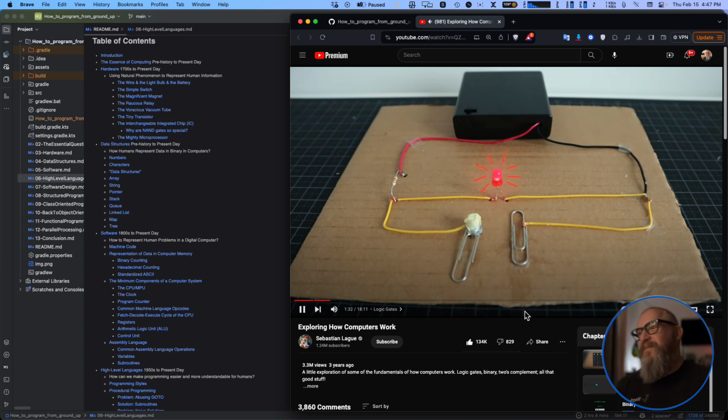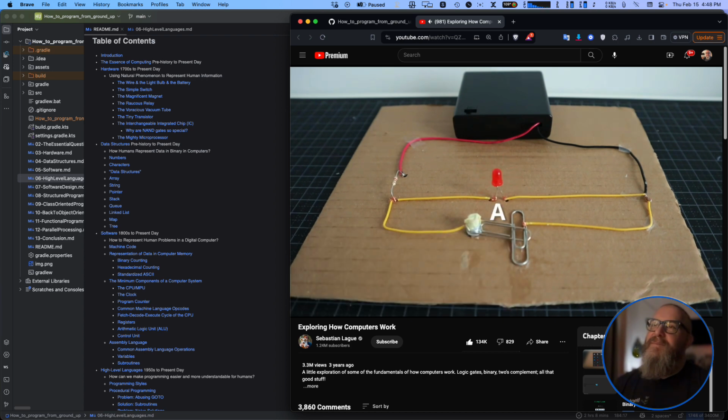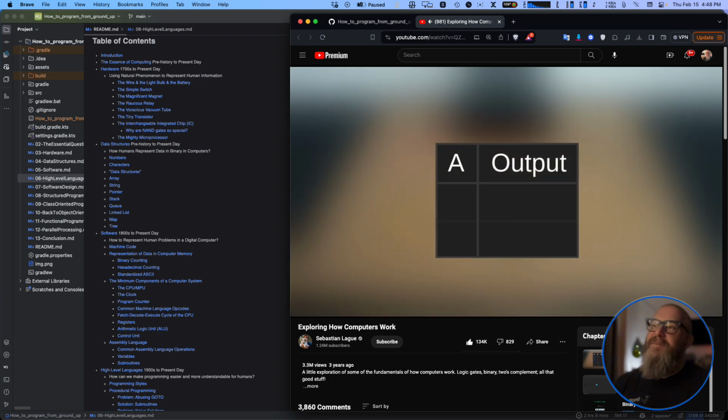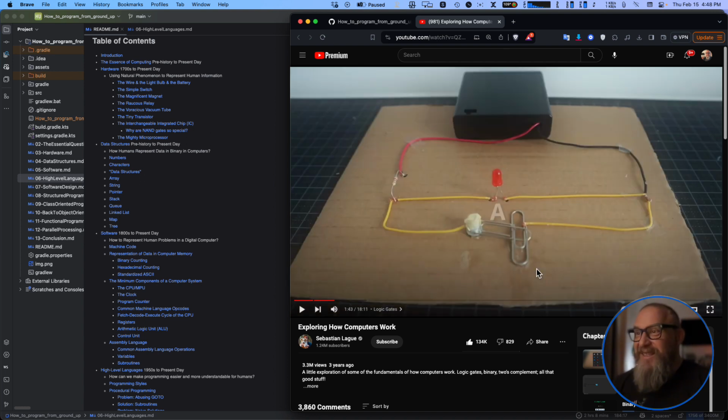A different circuit. This time we only have one switch, and even though it's open, the light is currently on. If I close the switch, now the light will go off, because we've created an easier path for the current to travel. So we're essentially inverting the input. If the state of the switch is 0, the output is 1, and vice versa. That's a very inefficient use of NOT, but it definitely works, because this connection is going to get real hot.